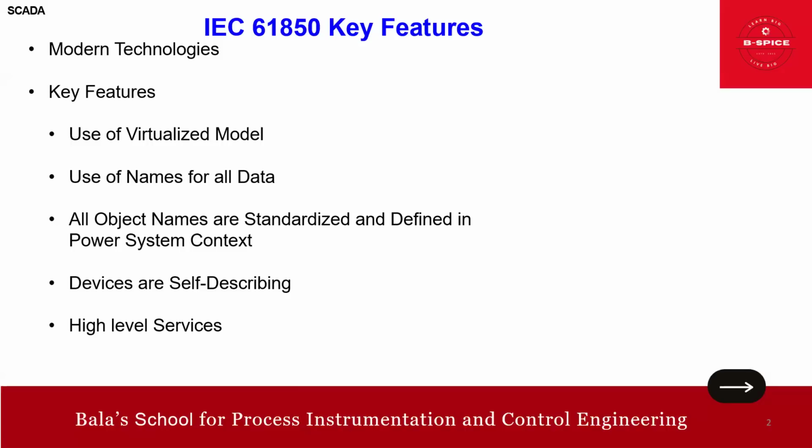GOOSE messages are transmitted within 4 milliseconds, making them suitable for time-critical applications like protection and control. It also uses a publisher-subscriber mechanism, where messages are broadcast to multiple devices simultaneously. It is also event-driven, so the messages are triggered by events such as changes in the status of a circuit breaker. Then of course very reliable, and vendor independent. That is the beauty of GOOSE.